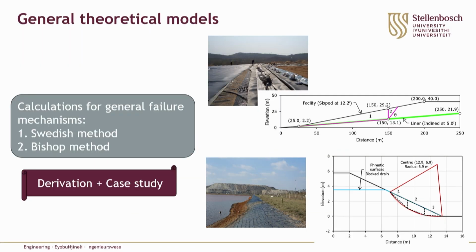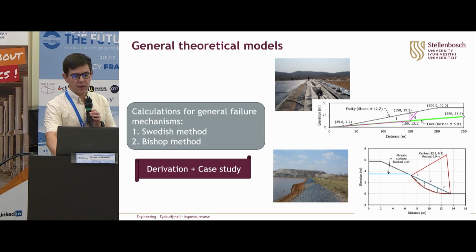The Swedish method, Bishop method, these are all fairly common. Derivation and case studies. For the Swedish method, we use a case study of an industrial waste facility that is lined. And for the Bishop method, we use an embankment dam that failed because the drains got blocked.